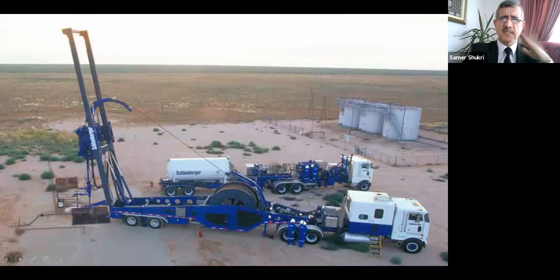So in this case, I stopped pumping nitrogen and waited until the station came back, and then continued the operation. In this case, we have to keep the pressure inside the coiled tubing higher than the pressure outside to avoid the collapse of the coiled tubing. Otherwise, the coiled tubing will collapse and be damaged.